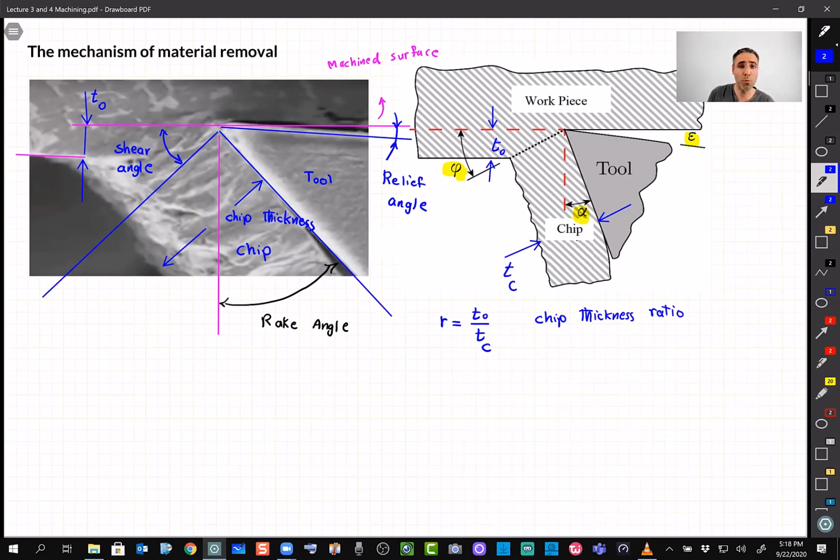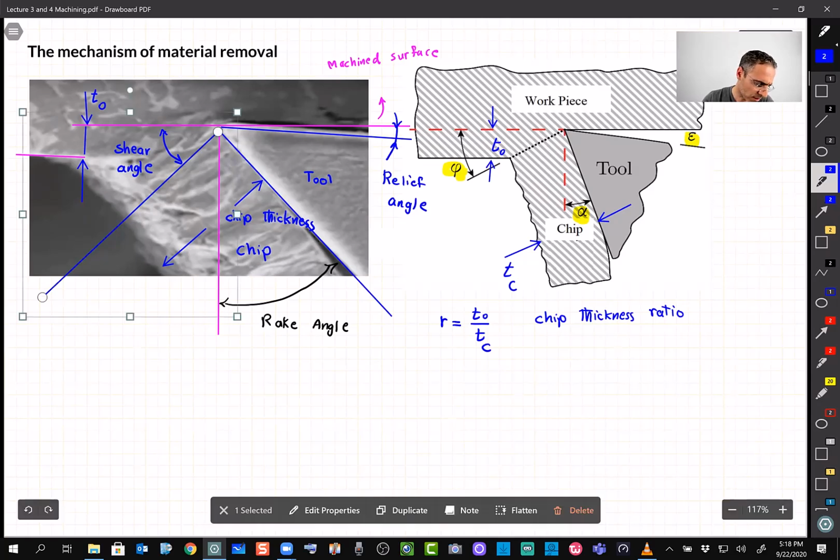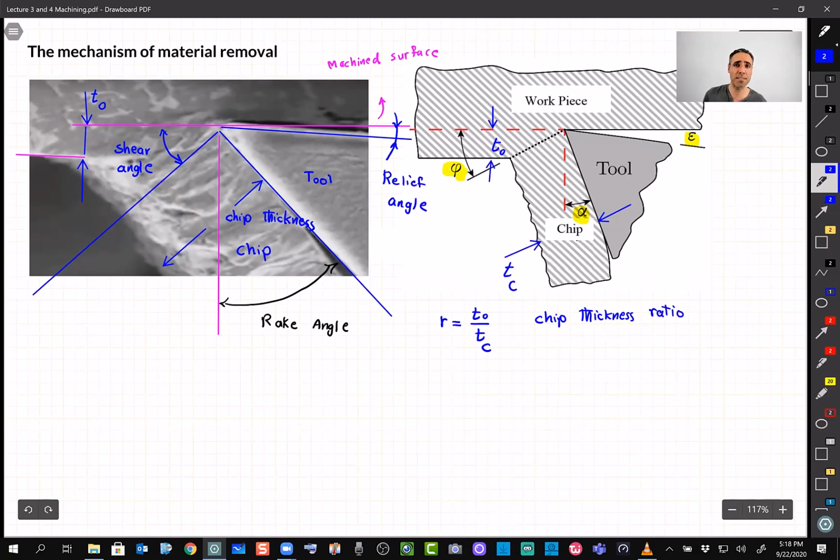Shear angle, we'll calculate it in a moment, can be equal to rake angle, depending on the angle that we set up, but it depends on the material. And yes, please remove that 90 degree situation there. It was just a special case. So it's not always equal. It can be equal to rake angle, but it's not in general. Does that answer your question?